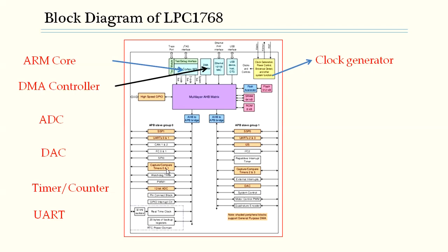There are two UARTs in the LPC1768, and in addition to the standard transmission and reception data lines of the internal CPU, the UART also provides a full modem control handshaking interface because it's asynchronous. So there are handshaking signals between the transmitter and the receiver. It supports the RS-485 protocol, which has a 9-bit mode allowing both software address detection and automatic address detection.